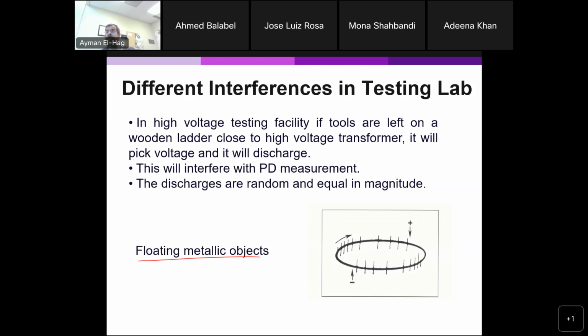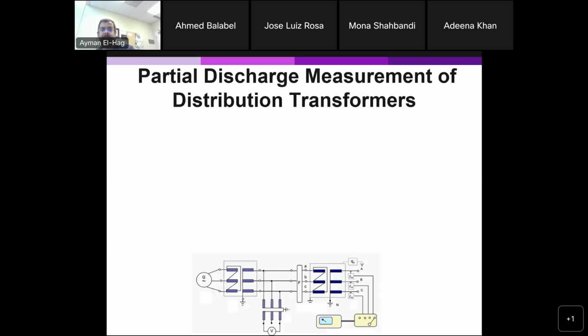Okay, so as you can see here, these are controlled samples. There is noise, and there are some problems that can happen, so the patterns are not easy to interpret. You need an expert to tell you what the actual source of the partial discharge is and what type of partial discharge it is. As I mentioned, now people are trying to use artificial intelligence systems, not to rely so much on the expert's opinion, but to rely more on the machine learning expert system decision.